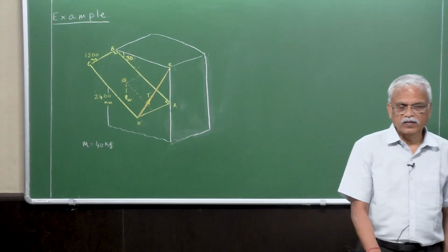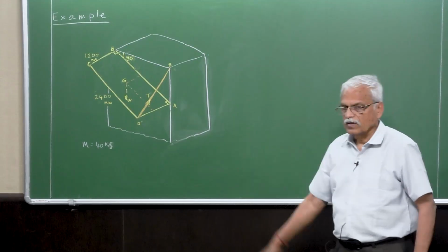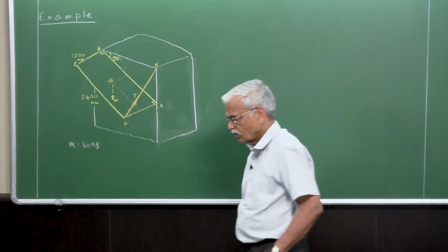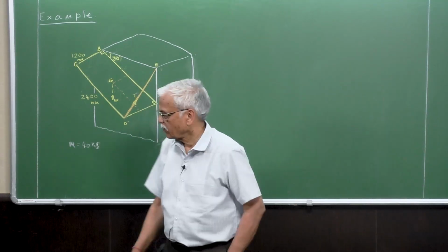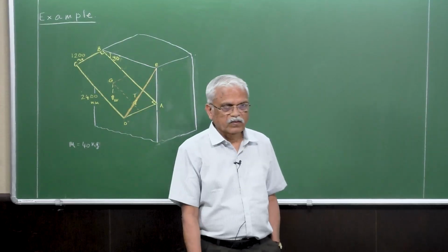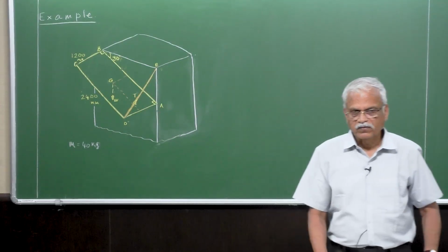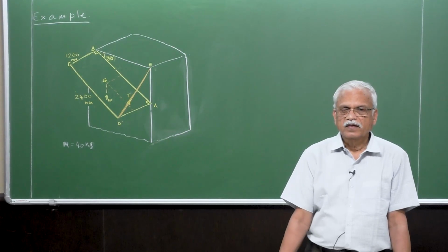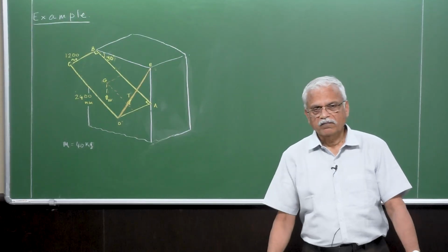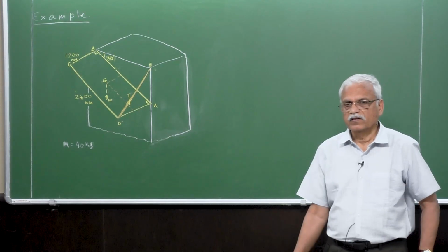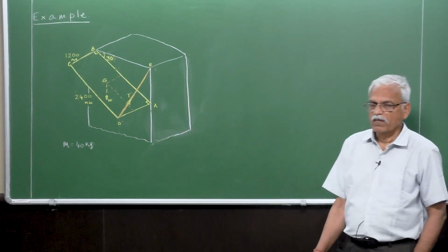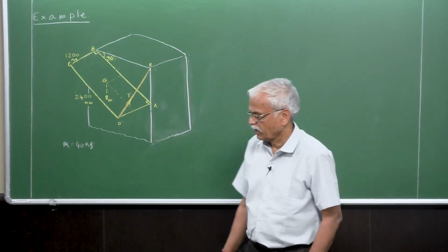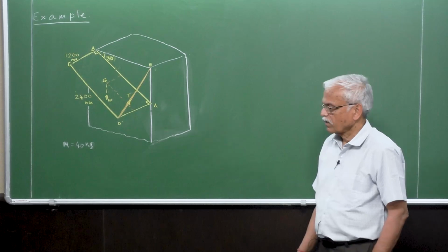So a single body, when it is acted upon by forces, if it is under equilibrium, we have 6 scalar equations. That means that sigma F is 0. Okay, all the forces should add up to 0, and similarly the sigma of all the moments of all the forces about some point is 0. So since both F and M are vectors, each of them is equivalent to 3 scalar equations. So let's try to draw the free body diagram.